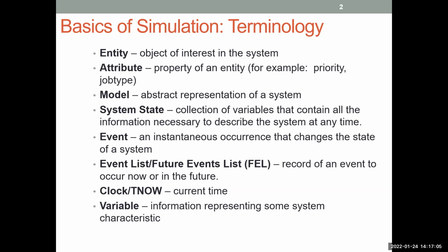For example, if you want to assign an attribute to an entity, such as the arrival time, you can use the TNOW variable to collect the arrival time for you and assign that to the entity. You assign the TNOW variable, or the TNOW-associated attribute, to that entity.